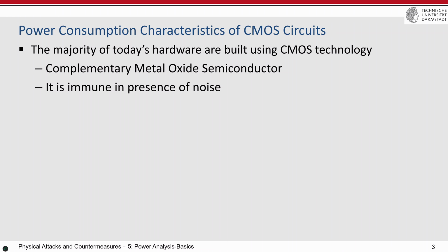If you remember, in the first session I explained the VDD of, for example, 65 nanometer technology is 1.2 volt. Then around 1.2 volt is considered as logical value 1, and something around 0 volt is considered as a logical value of 0. But then how about something in between?